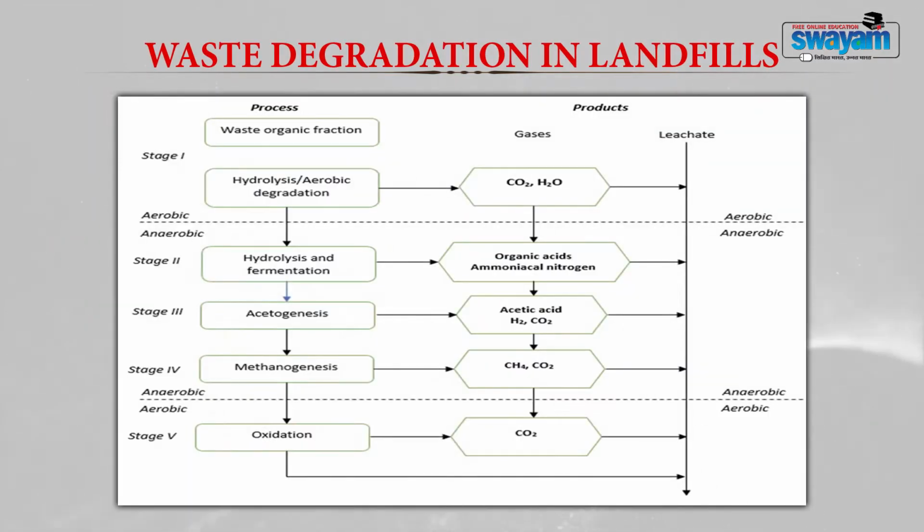Now, let us discuss the waste degradation that occurs within the landfill. You all know within a landfill, after the waste is loaded, certain physical, chemical and biological reactions take place in the waste matrix or waste material. The physical reactions will be just simple compression, settling, compaction and so on. The chemical reactions can be certain precipitation, redox reactions, oxidations that occur within the waste pile. Majority, if you see, the waste undergoes a biological degradation with the help of microorganisms, and this occurs in various phases.